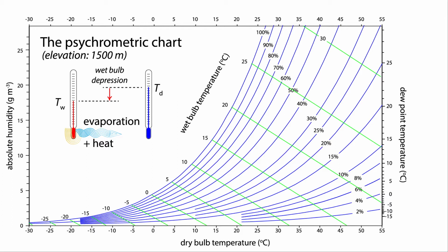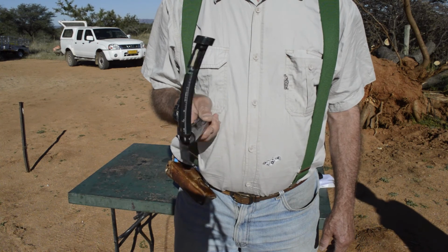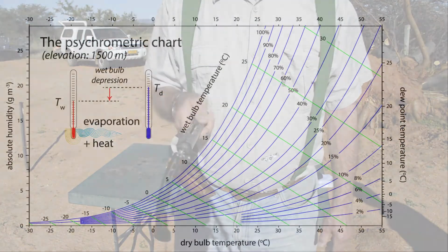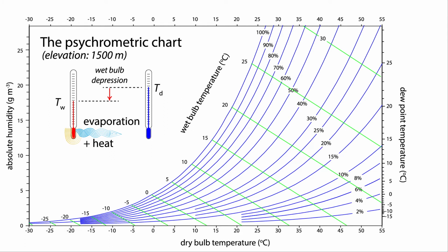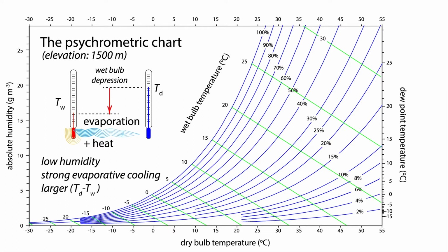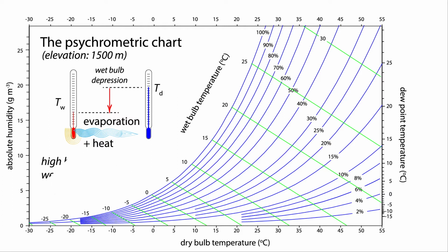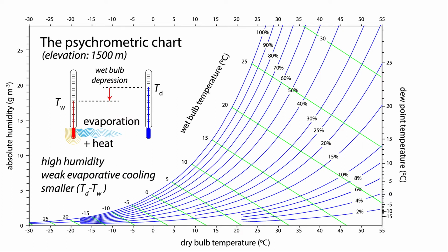Suffice it to say that wet bulb temperature is the lowest temperature attainable by evaporation into the ambient air by a properly ventilated psychrometer. Thorough ventilation of the thermometer bulbs is a precondition for correct reading of humidity. The basic point is that the wet bulb temperature is going to be proportional to the absolute humidity of the air. A low humidity will depress the wet bulb temperature at any air temperature because there will be a high evaporation rate, and therefore a lot of cooling. A higher humidity will produce less cooling, and the depression of the wet bulb temperature will be less.